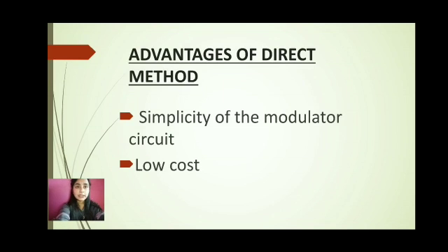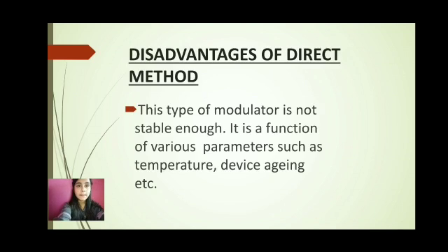Here are the advantages of direct method. First is simplicity of the modulator circuit. Second is the low cost. Disadvantages of direct method: it is not stable enough. It is a function of various parameters such as temperature, etc.